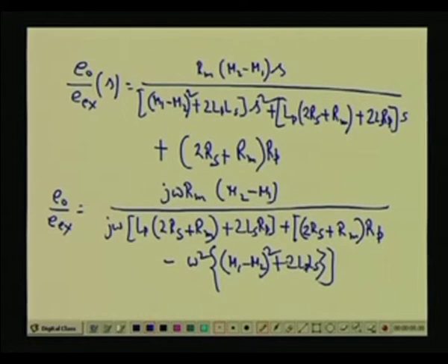See, now if I want to make the input output phase shift 0, then you see that this term, and this term will be 0. Then j omega, j will cancel out, so it will be only the real part, no imaginary part. So, there is no phase shift between input and output, otherwise there will be phase shift, right.